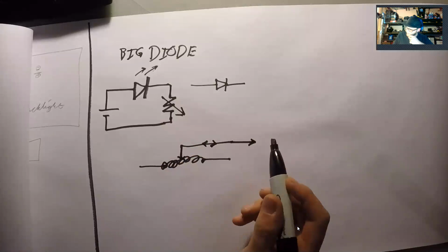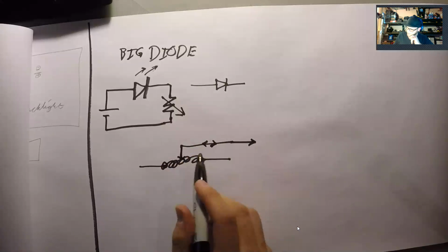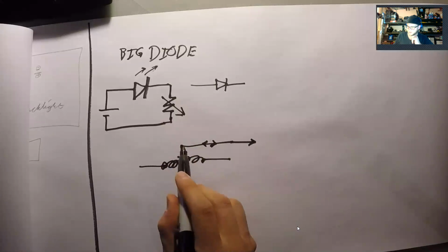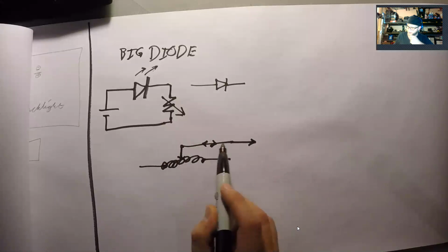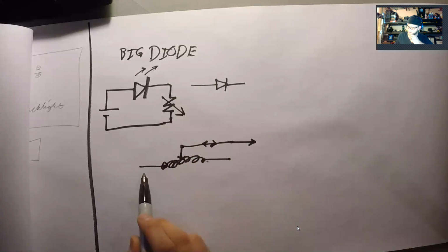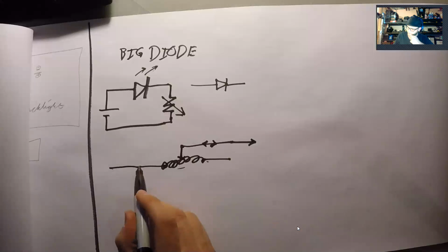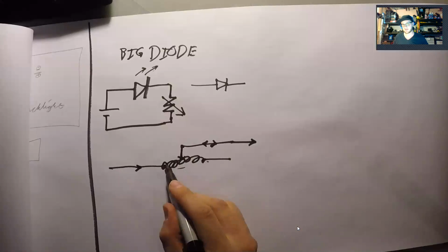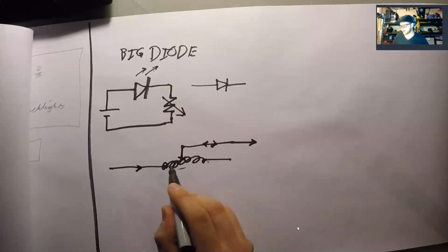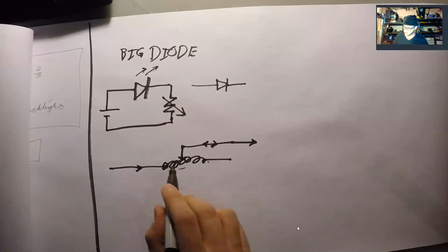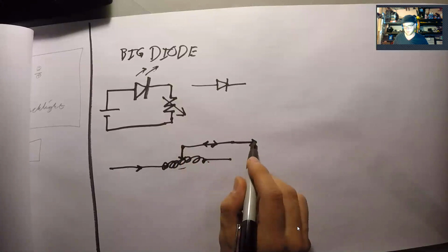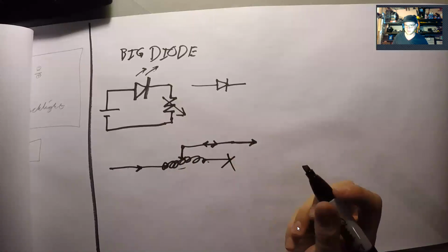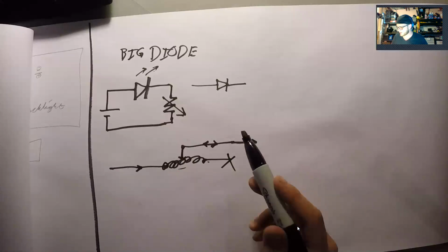And then it's got a wire lead coming off of it, right? And so you can actually move this wiper in and out along this wire winding. And so what happens is you have your incoming current, right? And then you're actually changing the length of wire that current is traveling through, because it's coming in, it's going up this arm and out here. Let's just say this isn't connected. Don't worry about that third leg.